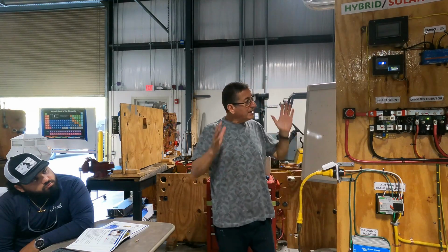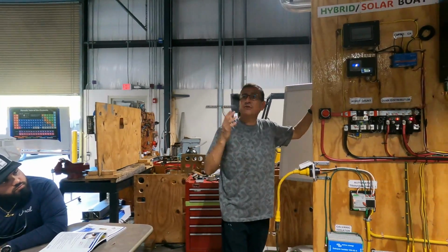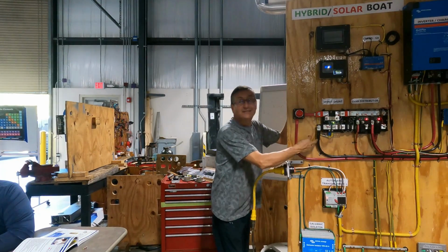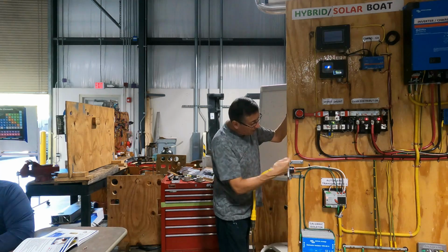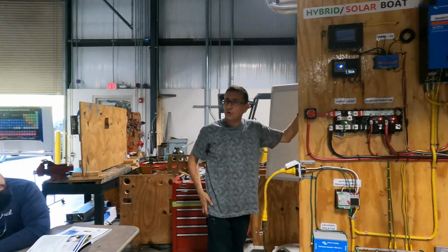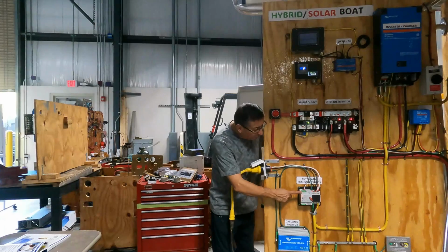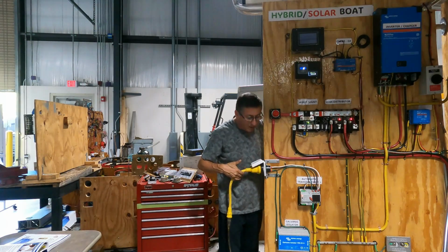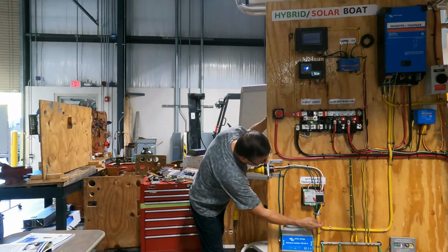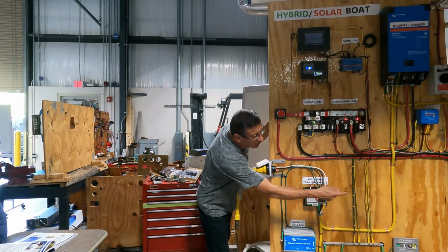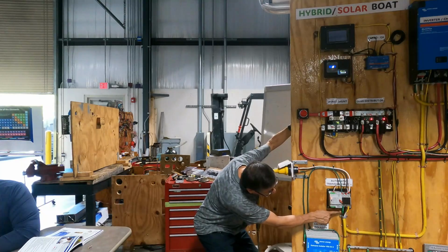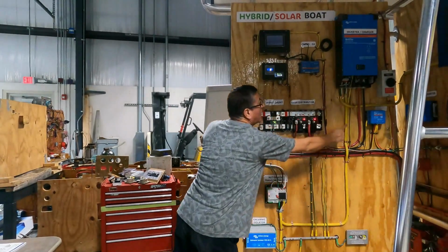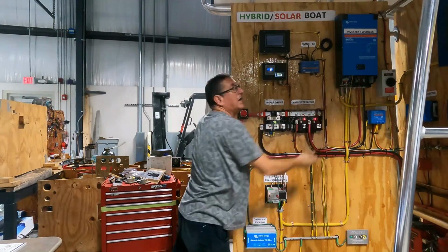In other words, in this moment in the system, I have two inputs of power for that inverter. One input is DC, and the other input is AC. Okay, look, the automatic transfer switch has an input of AC, hot, neutral, and ground from the shore power, an input of AC, hot, neutral, and ground coming from the generator, and in the back, another output, hot, neutral, and ground, coming out and entering here at the input of the inverter.